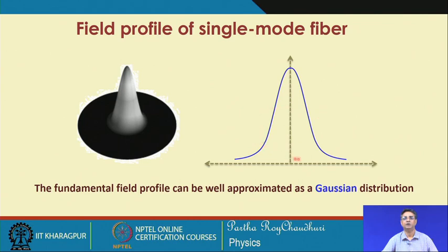That helps a lot in fiber mode matching, splice loss, butt coupling calculation and many other occasions. The mode field and the propagation constant are the two important parameters of any waveguide, which detail almost all guided properties of an optical waveguide.